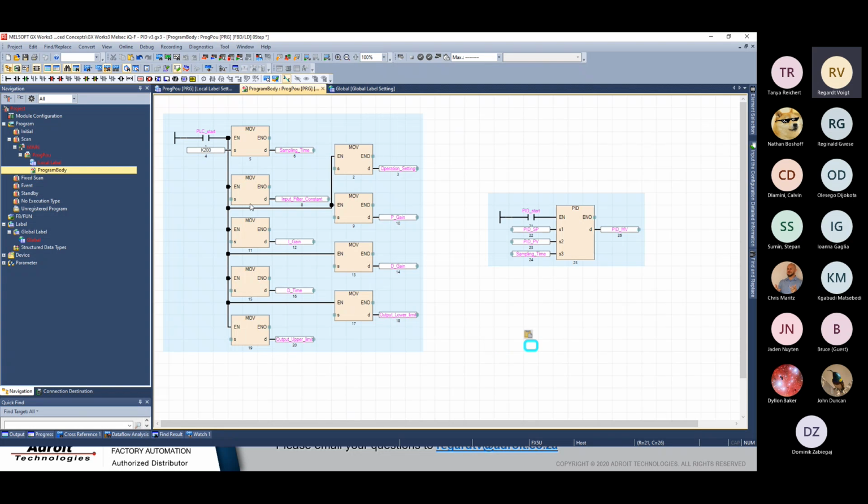Input filter constant, that will depend on your application, your installation, and so on. You can start with any value and you can adjust it. I'm just going to start with 70. Right. And then I'm going to use an I gain of 100.